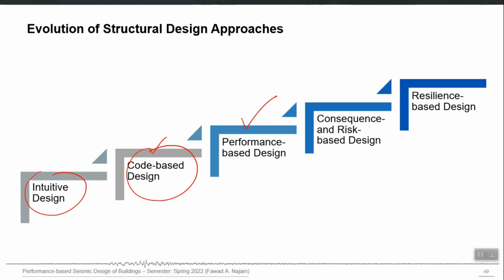But at least when we have developed well researched building codes, the resulting design is better than the intuitive design. But performance based design philosophy is one step beyond those code based designs, right? It gives you that freedom and flexibility to try new procedures and go beyond the codal requirements.